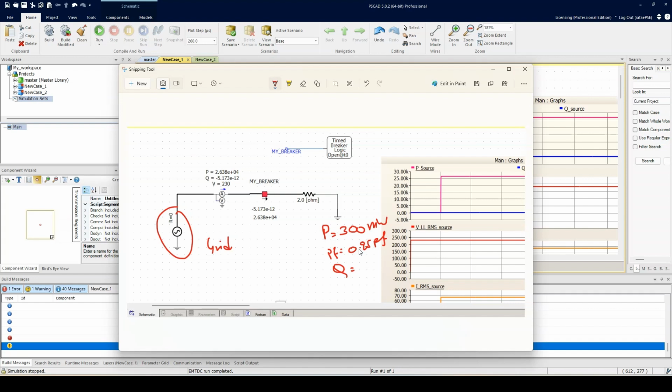I'm just going to assume something along the lines of 300 square. Okay, so let's assume 98.6 MVAR. Okay, and just to keep things simple, I'm just going to assume it equals 100 MVAR. Okay, and that's what you're given. You're just given P equals 300 megawatts. Power factor is this, which in return, let's say the Q is equal to 100 MVAR, or precisely whatever that turns out to be. You can perform that calculation as well, which is not too far out from 100 MVAR.